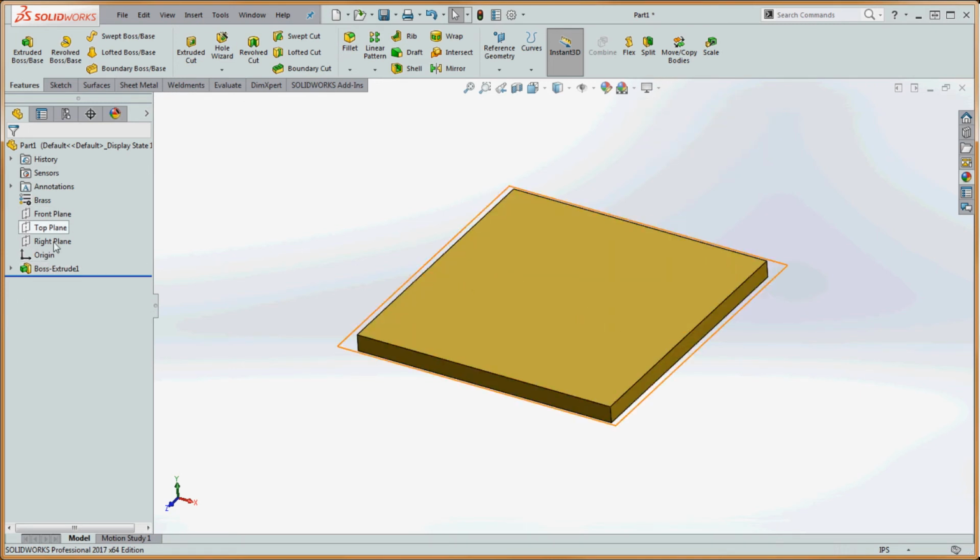Let's go to our feature. You can rename all your features and your sketches. Typically in sketches, I leave the names the way they are, Sketch 1, Sketch 2, and so forth. SolidWorks automatically just adds another number to that incrementally, so as you move down your Feature Manager tree, all your sketches are going to be in order. But sometimes, like with lofts, when I'm trying to distinguish planes and sketches on those planes, I will actually name those. And with sweeps too, one for the profile, one for the path.